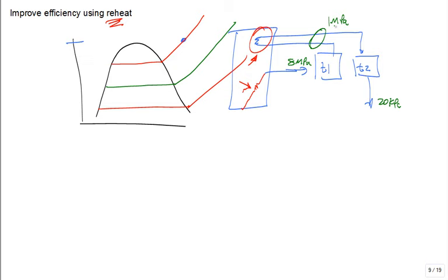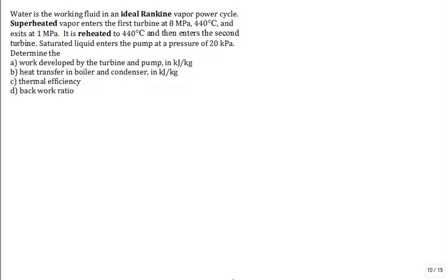So you stop the temperature because of metallurgical considerations. You expand it. Maybe it expands into the 2-phase region, maybe into the superheated region. For maximum efficiency, probably it's really close to saturated vapor, probably inside the dome. And then you could reheat it back up to that same temperature again, and then expand again. Okay? So that's the concept of reheat. I probably should have shown it on a real diagram, but we'll do that in a minute. Right here. That was a short minute, Professor.